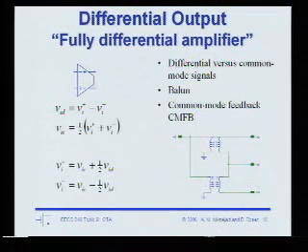So here, if I come in with two input signals, this node is only sensitive to the common mode signal. If you're familiar with baluns, this is very obvious. If you're not, you might want to take a little bit of time and analyze this circuit. This signal here is, in essence, the difference between these input voltages, so it is the differential input voltage. And I can use it the other way around. I can apply a voltage here, and this will give me a differential signal over here. And if I apply a common mode signal, that gets summed onto both of these terminals. So in SPICE, you can use a little building block like this and just put it in your library.